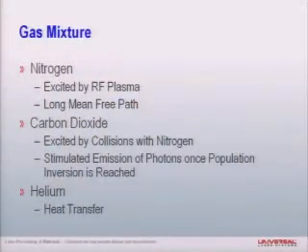So I mentioned the gas mixture. A typical mixture might have 70 to 80% nitrogen. It's the nitrogen that's actually being excited by the RF. And the reason nitrogen is chosen is because it has a relatively long mean free path. So it's likely that it's going to hit a CO2 before it recombines with another nitrogen and falls back to the ground state.